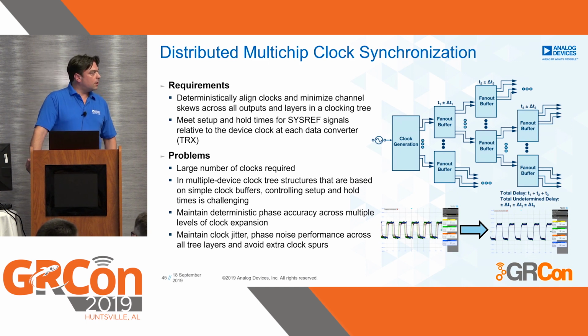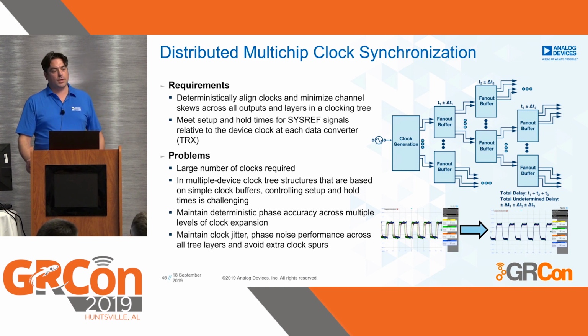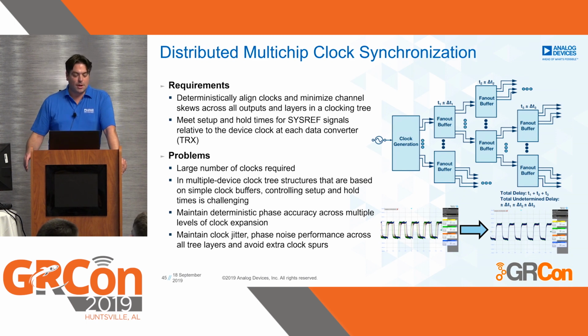In a multiple device clock structure based on simple clock buffers, controlling setup and hold can sometimes be really challenging. And of course, very important is that you maintain a deterministic phase across multiple layers in your clock hierarchy, while maintaining clock jitter and phase noise, and you don't want to add additional clock spurs to your downstream devices.